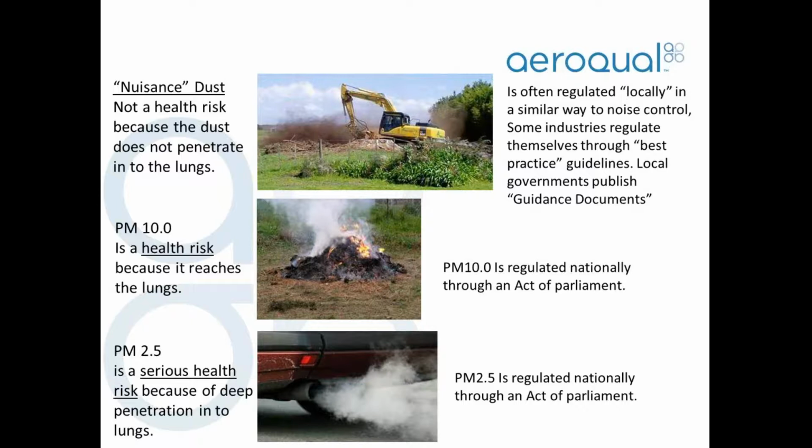Now, this is different in different countries and different regions, but generally speaking, dust tends to be regulated by local rules and regulations, municipal rules and regulations. Dust is often regulated in a similar way to noise control. Some industries, construction industries or demolition industries, will regulate themselves through best practice guidelines, and some local governments publish what might be called guidance documents on the regulation of dust.